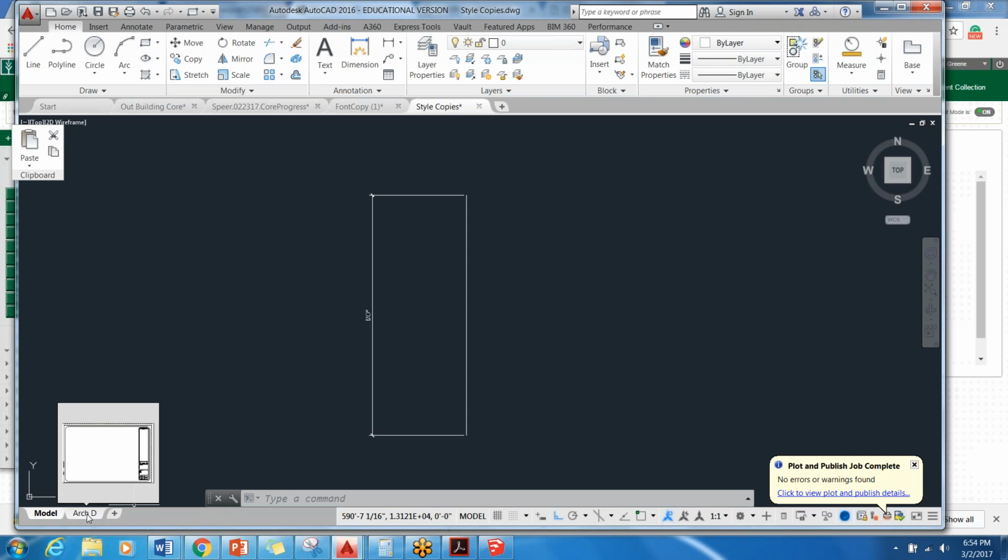It's like I have to know that if I'm in here, I'm going to be printing at 1/4 inch, and then it'll end up being at 1/8 size architectural scale because I use 6 inches in model space using that chart. It's super technical. I think we could review it another time if you'd like to. It might make more sense when you're doing it with conjoining the row to the column for your homework.